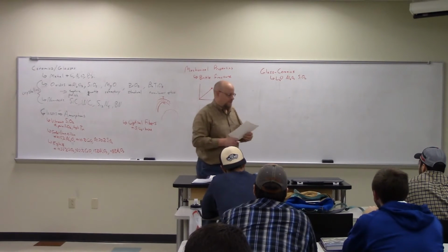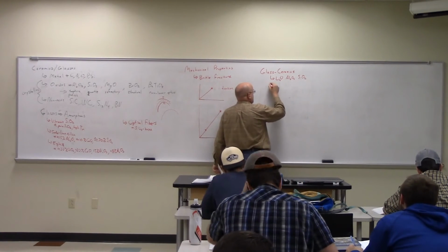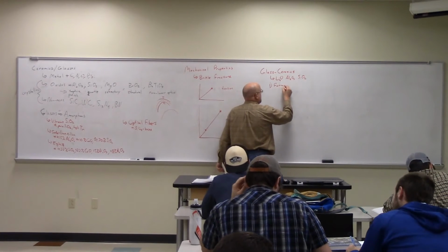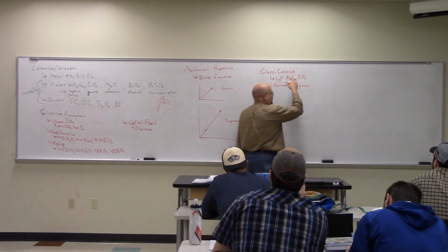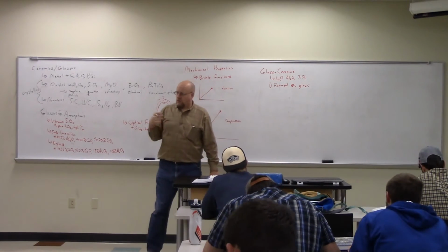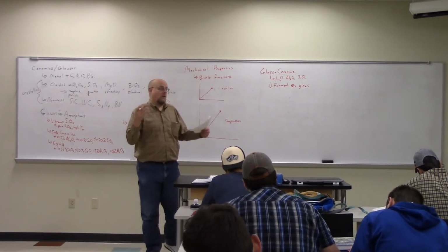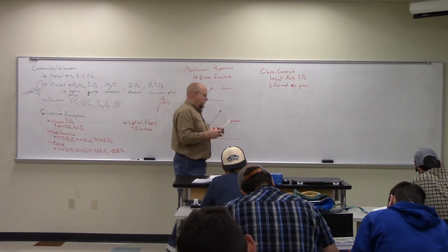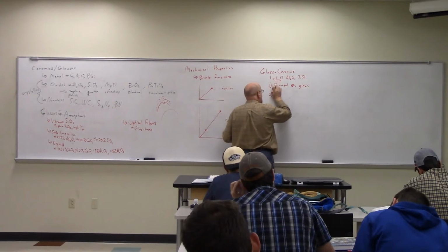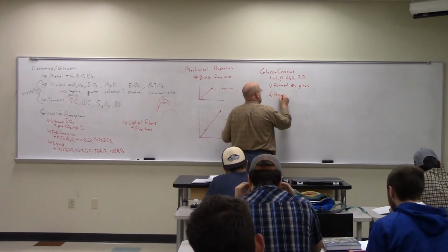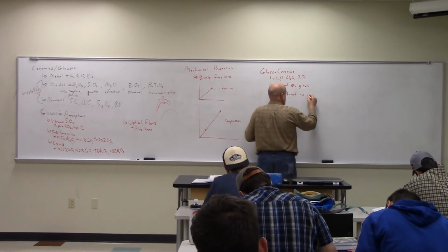And what happens with this stuff is, I guess the process is, it's formed as a glass. So you take an amorphous version of this and you form it to the shape you want as a glass, as you blow it, like a glass blower, into the glass shape. Then you heat treat it to induce crystallization.